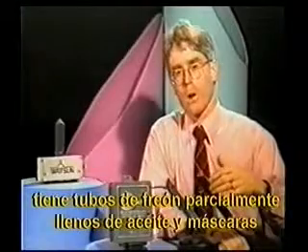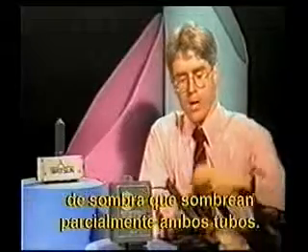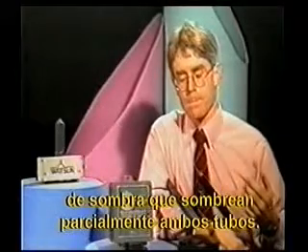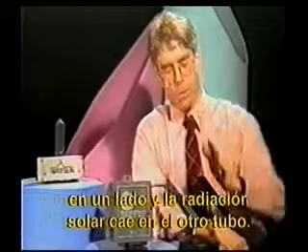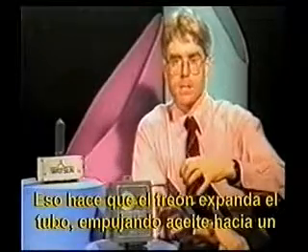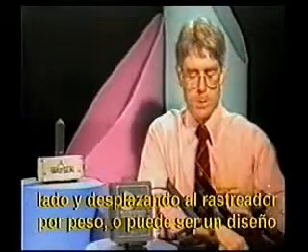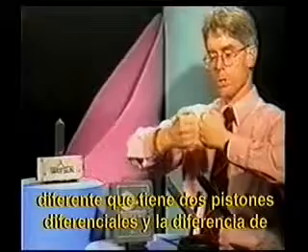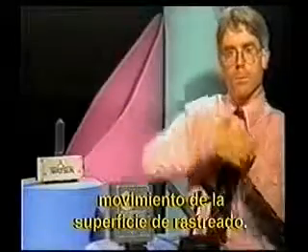The design of the tracker involves Freon tubes partially filled with oil and some shadow masks that partially shadow both tubes. As the sun moves throughout the day, a shadow is cast on one side and solar radiation falls on the other tube. That causes the Freon to expand in the tube, pushing either oil to one side and displacing the tracker by weight, or we might have a different design that has two differential pistons, and the pressure difference between the two tubes causes a movement of the tracking surface.